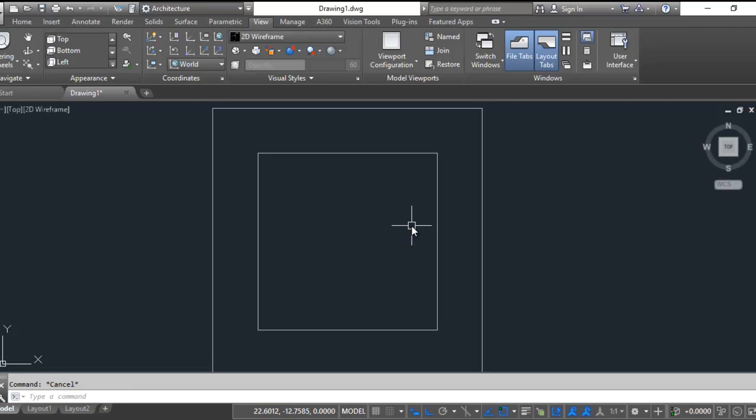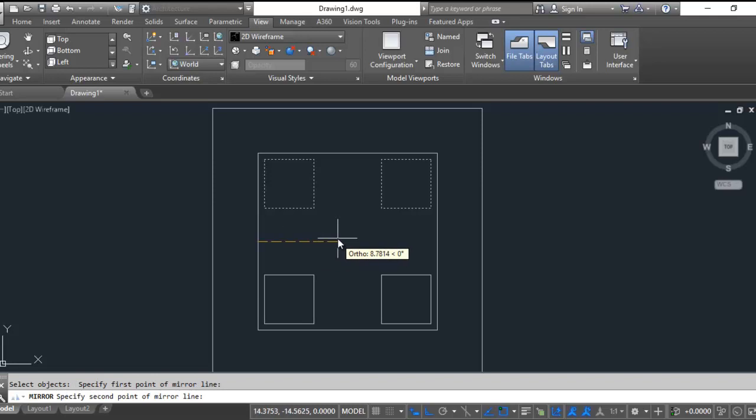Now to make our partitions, I believe I'm going to do maybe 5.5 by 5.5, and that would be moved. I'm going to move it 3/4 of an inch down and 3/4 of an inch to the right, assuming we have maybe 1/8 we're making these partitions out of. Mirror those guys around. We'll need another one here that's maybe 6 by 5.5, 0.75.